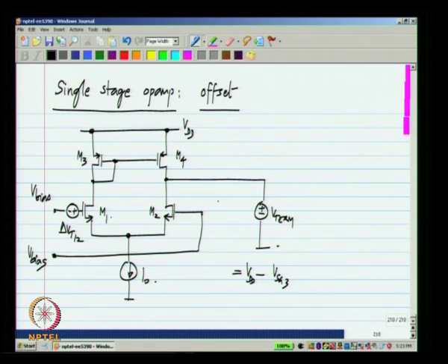As with noise, the polarity of this is not important because we know that it is a random quantity. Finally, what we will calculate will be the standard deviation or the variance of this quantity. Now, what is the output current due to this voltage source? It is very easy. You can see that delta VT is simply the differential input voltage to the op amp. This is where we normally would apply the differential input. So, the output current is simply GM1 times delta VT12, the transconductance times delta VT12.